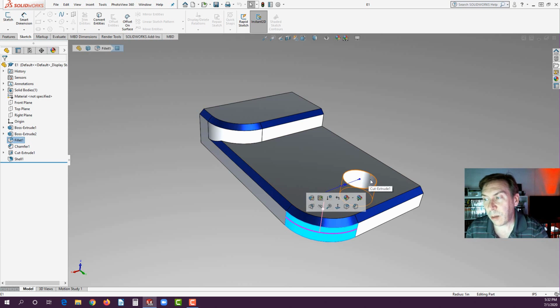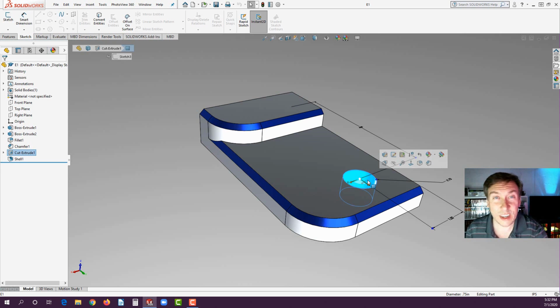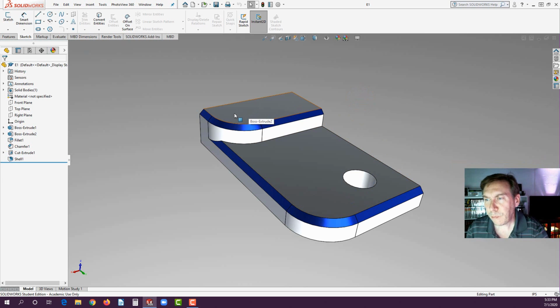Okay. We're going to put in some stacked extrusions, 1 and 2, and we're going to put in this hole that you see there using what's called a cut-extrude. There is a hole tool inside here, a Hole Wizard actually. It has all sorts of neat holes like counterbores, countersinks, pipe taps, you name it. But we're not going to go into that today. We'll probably hit that in the next couple of weeks with exercise 4. All right, so let's get started.